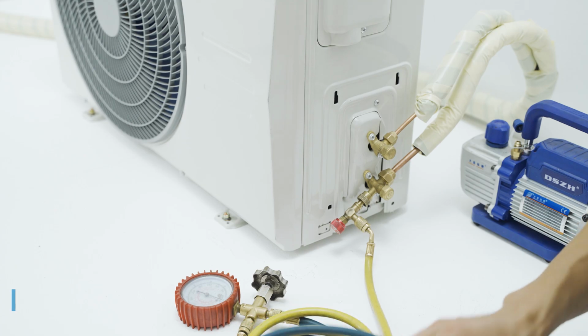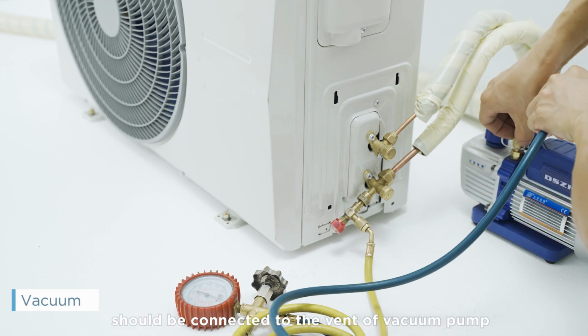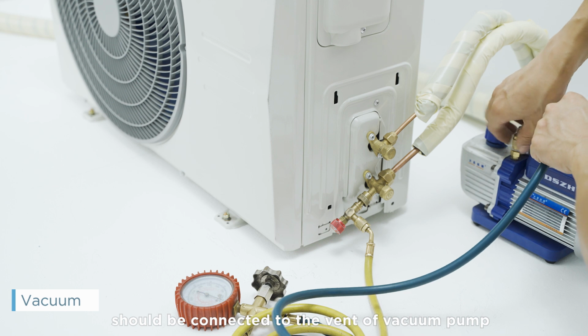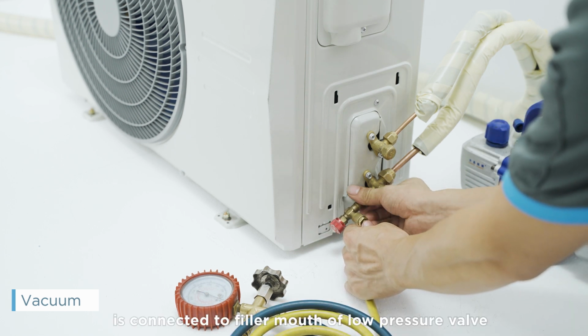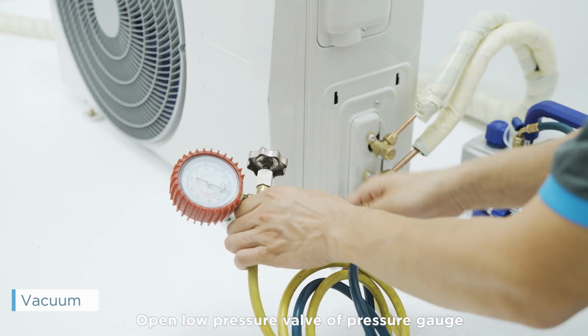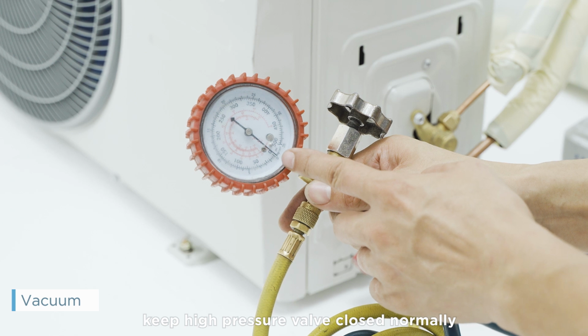Vacuum. One end of the filler line of the pressure gauge should be connected to the vent of the vacuum pump, the other end is connected to the filler mouth of the low pressure valve. Open the low pressure valve of the pressure gauge. Keep the high pressure valve closed normally.